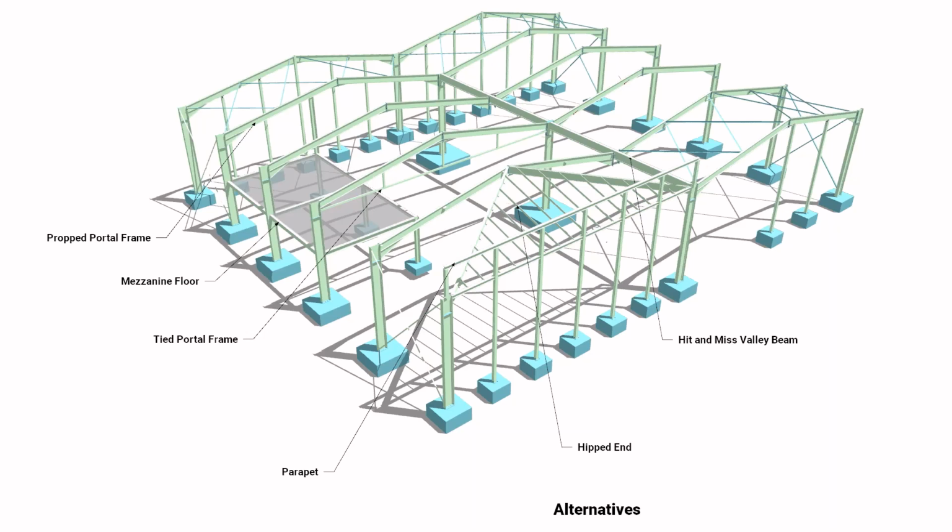I haven't shown other arrangements such as ones which have an overhead traveling crane that can be incorporated and must be considered a part of the primary design, nor mansards, which is sort of an arched portal frame using 4 rafters instead of 2, but this is available within MasterPort.